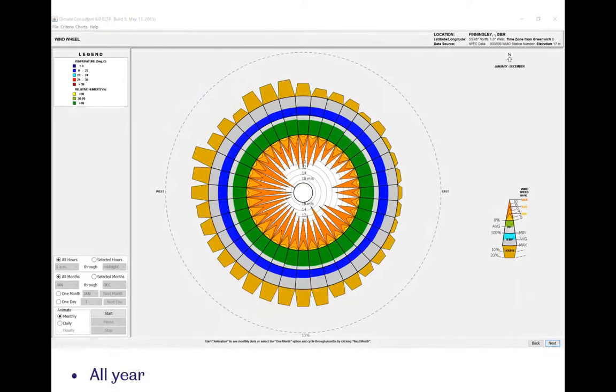So if I go back, this is the whole year for Sheffield, and what you see is the winds tend to be stronger in the south, southwest, and the west, but you get wind from all directions all year round, effectively. Some sites you get a much more directional wind. So probably, if this was your site, you might quite reasonably decide that you're going to test from a range of directions, because the wind comes from all over.